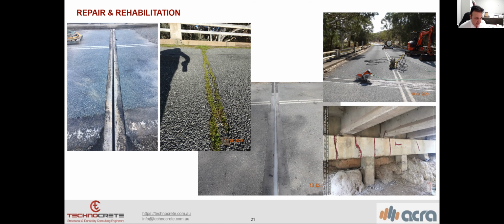The deterioration rate of ASR can be accelerated by increasing the temperature and increasing the moisture available. Then water could easily penetrate through the expansion joint and reach the pier and crosshead of the bridge, and then the deterioration which we saw.